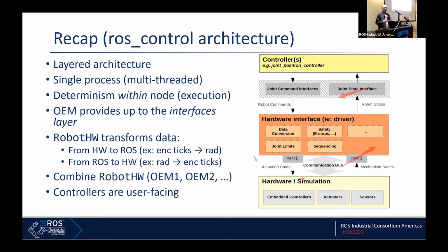However, controllers are the ones who know what to say to the robot. So the controllers are where the main magic happens. Here the hardware interface of the robot gives you the transformation of the real-world data from the hardware to ROS. The controllers are the main logic of this entire system.